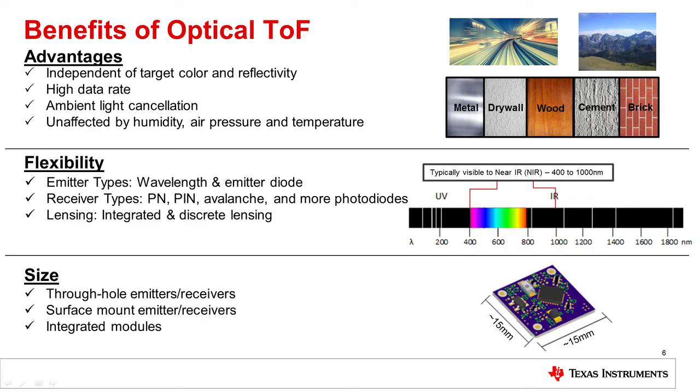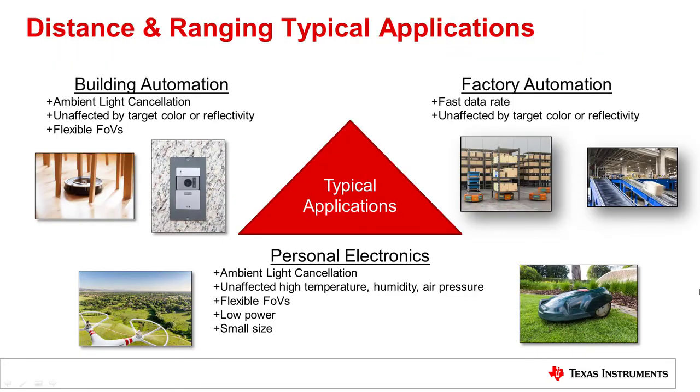With all of that in consideration, optical time-of-flight technology can reach ranges from a few millimeters to several meters. The resolution can also be a few millimeters based on several factors such as the lenses selected. Power, though dependent largely on range and field of view, can be low enough to be operated in battery power applications. There are many applications that work extremely well with optical time-of-flight.